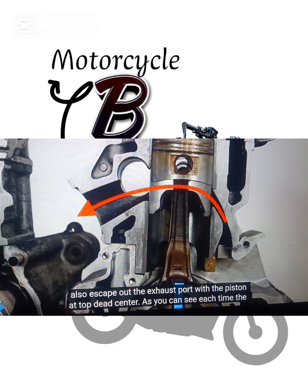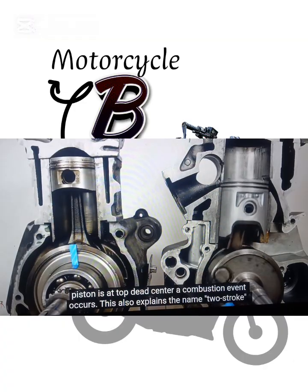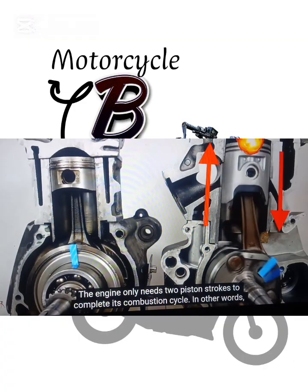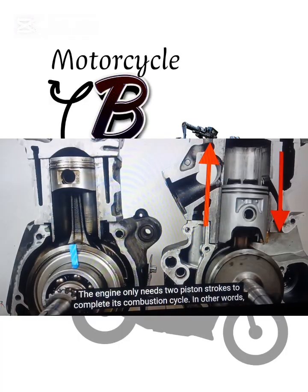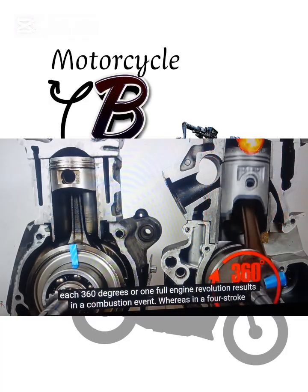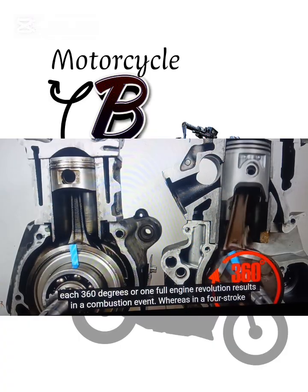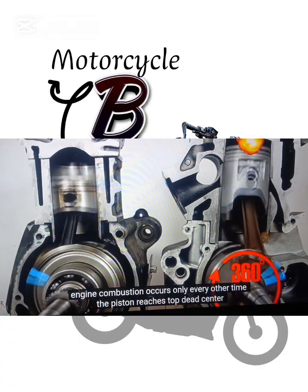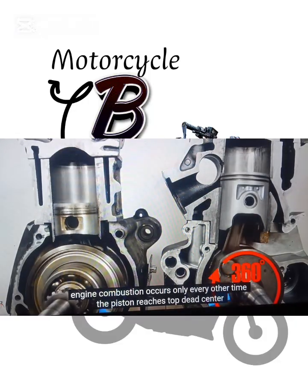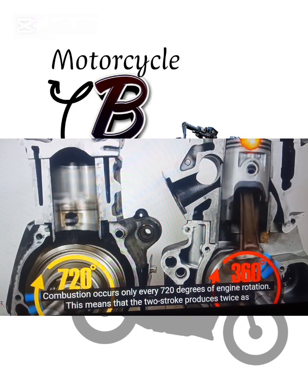As you can see, each time the piston is at top dead center, a combustion event occurs. This also explains the name two-stroke. The engine only needs two piston strokes to complete its combustion cycle. In other words, each 360 degrees or one full engine revolution results in a combustion event. Whereas in a four-stroke engine, combustion occurs only every other time the piston reaches top dead center. Combustion occurs only every 720 degrees of engine rotation.